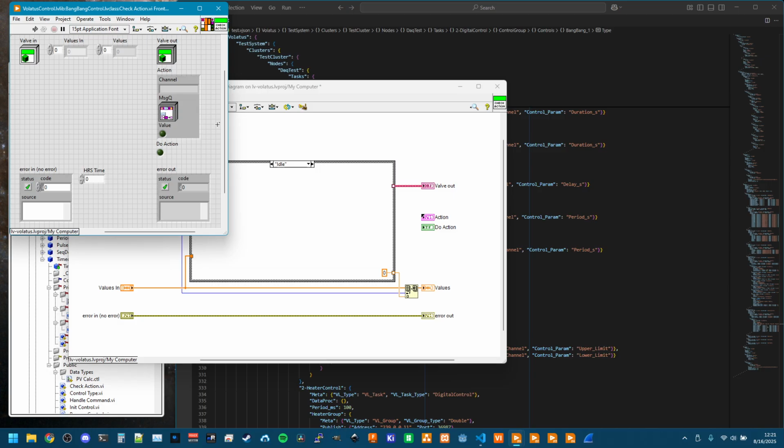So it guarantees that anything for that control iteration that updates values handled by the same module. For instance, a digital output module is going to have a whole bunch of channels it's outputting. Typically, if you're using a 9403 or 9476 or one of those different serial modules, they've got 32 channels in them. So very likely that a whole bunch of these digital control components are going to be coordinating controls for several of those output channels simultaneously.